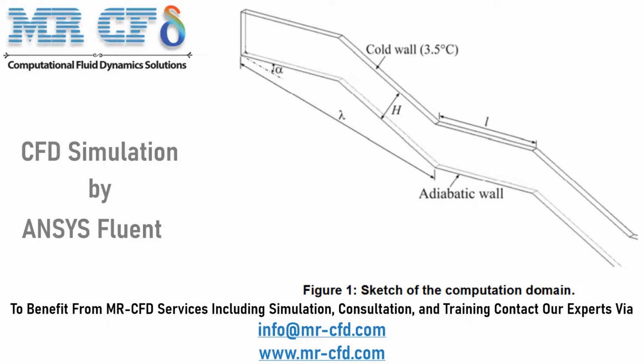As you can see in this slide, we have extracted the figure 1 of the paper, which shows a model of zigzag channel used in the paper. The channel model is such that the number of stages of channel oscillation in the horizontal direction is equal to 10, and the angle of channel in each of these 10 stages for modeling is assumed to be equal to 15 degrees. Several different Reynolds values, including 53, 107, 191, 266, 320, and 427, were used for this simulation.